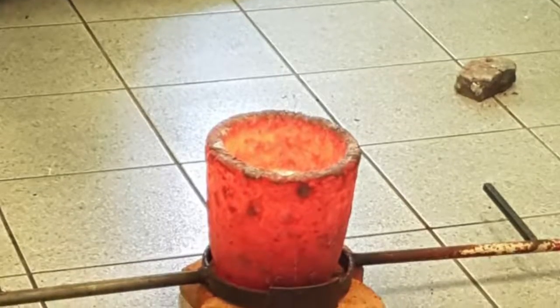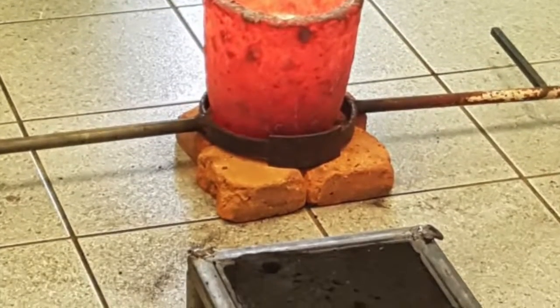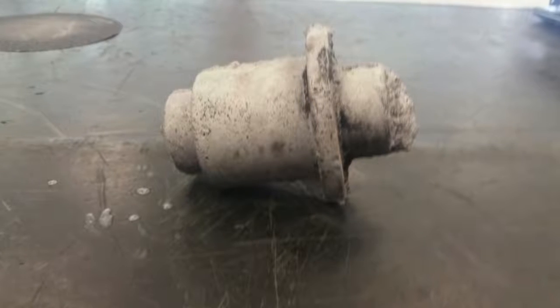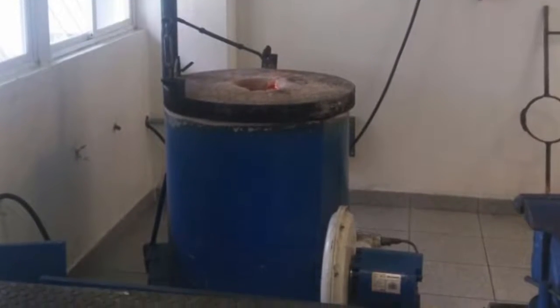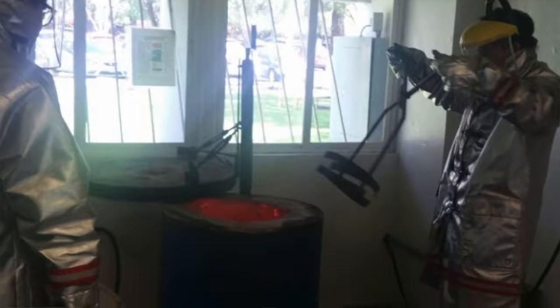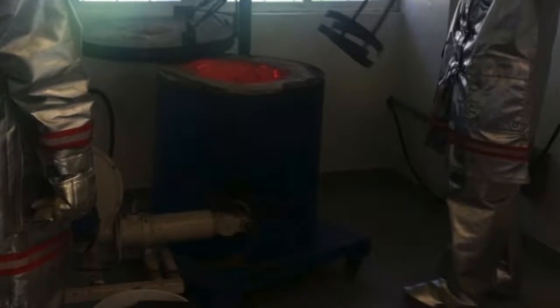Practice 2 is casting process in green sand. The objective is to melt aluminum alloys in a melting pot to understand a process from the scrap to the finished product. We will use aluminum components, and for the equipment we will use melting pot, molds, furnace, and casting tools, and also we will be using safety equipment.